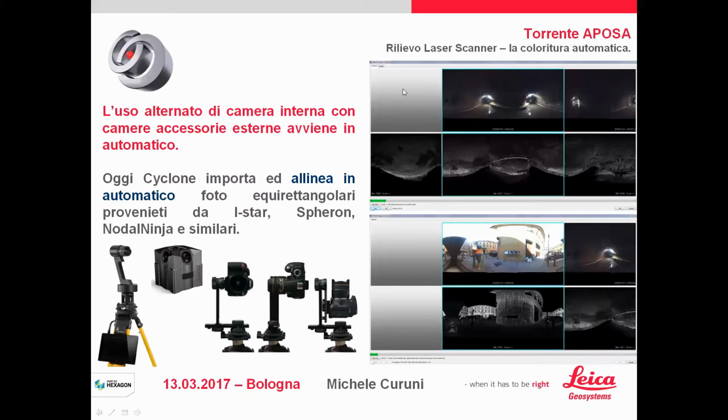Okay, and these are two screenshots of the software that can automatically align the images. The upper line is the color spherical images, and the bottom line is the spherical image of the point cloud generated in grayscale. Then you accept the common pictures, and after clicking about 30 points, you click load and the software runs and automatically aligns the spherical images of the pictures with the spherical images of the point cloud.